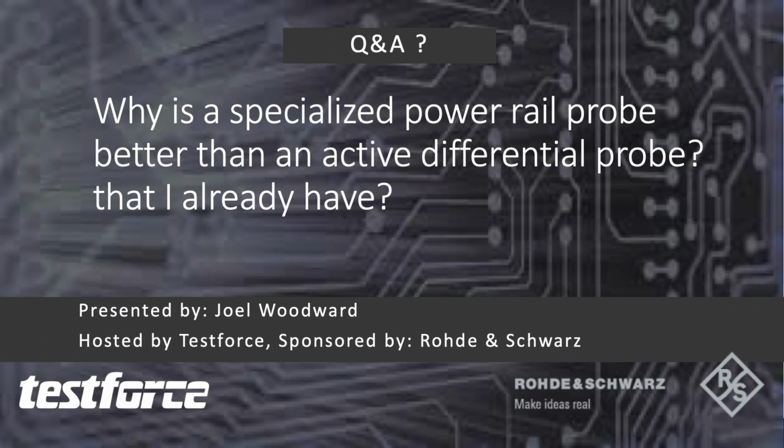Next question is, why is a specialized power rail probe better than an active differential probe that I already have? Really good question. Power rail probes are designed with a 1-to-1 attenuation for very low noise. Differential probes that exist in the market outside of this typically are able to see higher peak-to-peak voltages, but they also have more noise associated with them because they don't have a 1-to-1 attenuation.